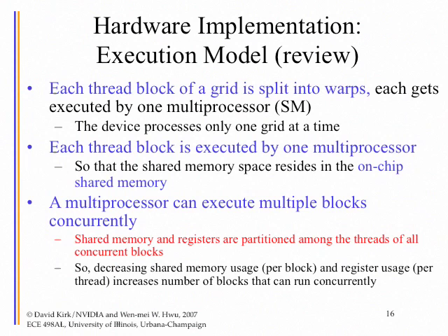Let's say I use 11 registers per thread, what's going to happen? How many registers are we going to use? Someone give me a number. 8,448. Is that number bigger or smaller than 8,192? Bigger, right? I'm not going to insult you by waiting for you to answer that. It's bigger. So we have a problem. We don't have enough registers in that case.